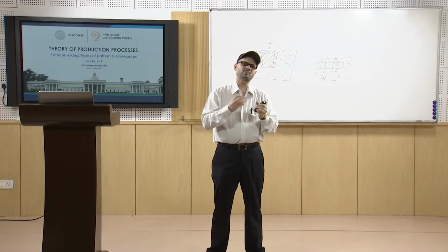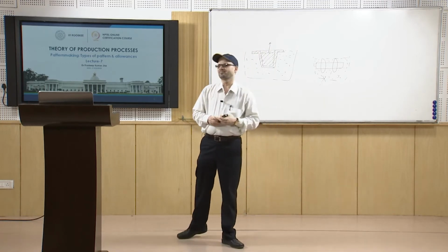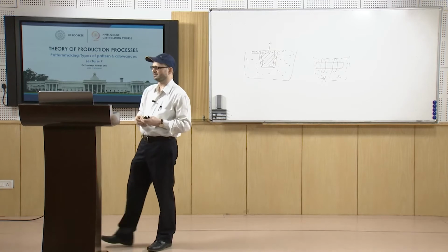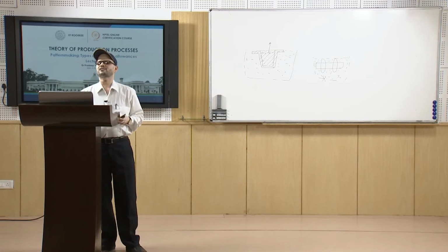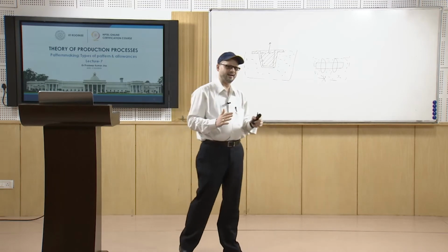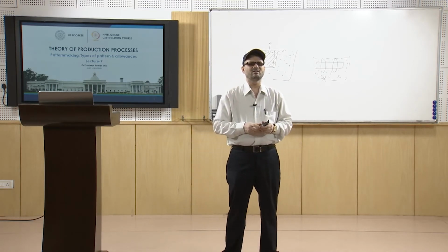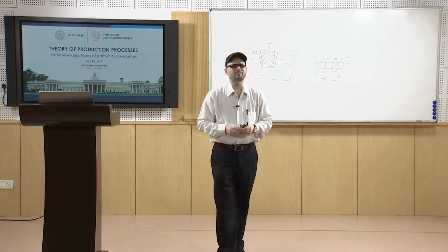if the component is smaller in size, in that case you have this pattern type known as match plate pattern, where you just invert on the other side, and on the other side you have the pattern for the drag part.